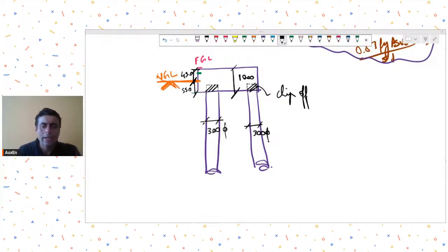We break some portion of the pile because during the pile concreting, there is a possibility that some soil substances or some deleterious matters may fall into this pile hole or pile bore.